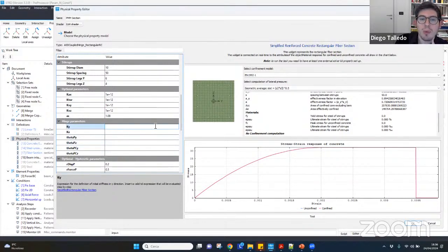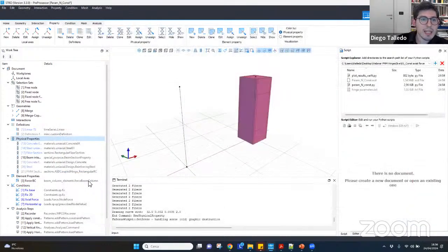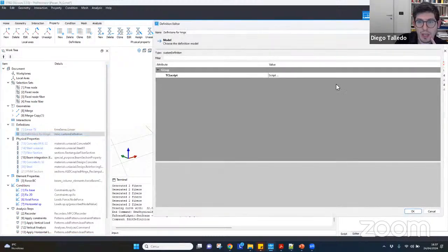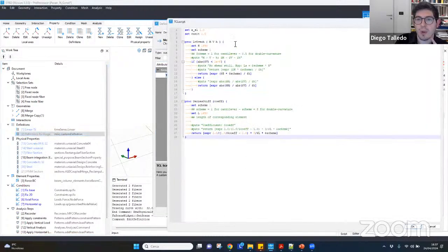Okay, so here we need to input some equations in valid Tcl expressions that will be evaluated at each step by OpenSees. So as I mentioned before, permit me to press OK and keep it saved like that. As I mentioned before, we can use previously defined user functions. So you will find in the file a definition for a hinge X object that inside contains some Tcl code.